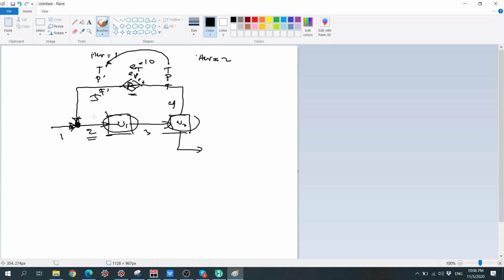So you will see that later on, whether we can see how robust the current simulation is. Especially in this reactor, for example, it's a function of dCA/dt, and it's a function of k exponent minus E/RT, right? You can remember this. And in our case there's also a partial pressure of methanol, for example.